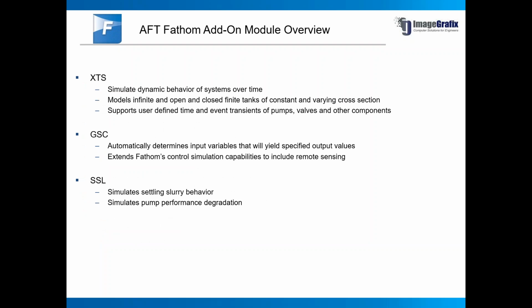So if you're doing any transient calculations, AFT Fathom is a steady state package, and if you wish to do any transient calculations, it can be done with the XTS module available with it. So with this, typically the system will be transient in nature. For example, you have a pump which is working at a fixed volumetric flow rate, discharging to a tank which is of specific volume.